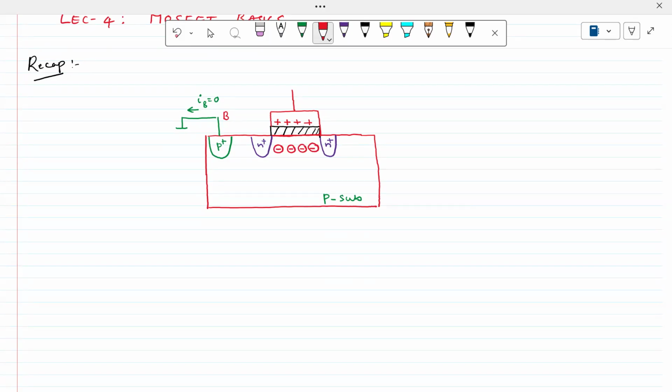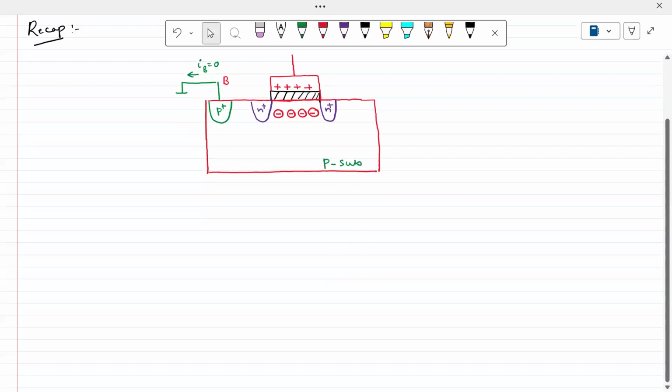Because of the positive potential at the top, all the free carriers are depleted towards the bottom side of the P region. Therefore it has immobile ions. If you increase further here, what will happen? Further depletion of the carriers occurs. Therefore, we observe that this is an immobile charge. Again, the insulating material also has immobile charge.